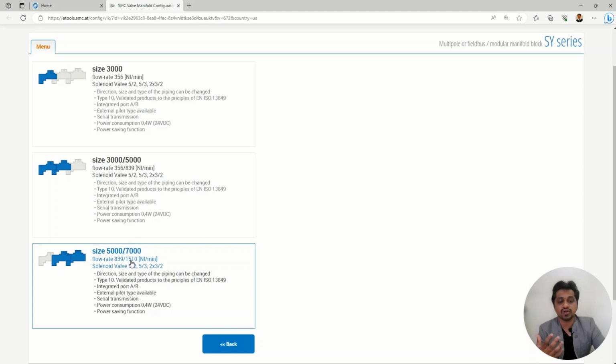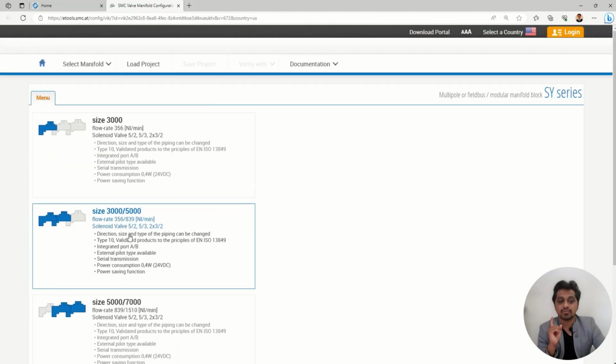You can check out the flow rate values, right? So if you want larger size valves, you can go for size 5000 and 7000. If you want lesser, you can go for 3000 only, or you can go for a combination of 3000 and 5000. So let's select SY 3000. You can go for combinations also.